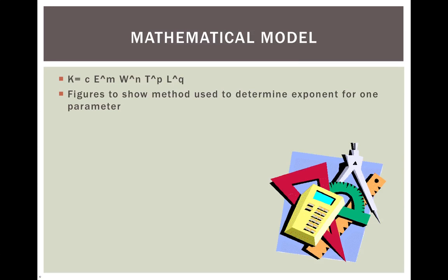But we do not know the values of the exponents for M, N, P, and Q. Given the equation, we figured we should solve it like any other algebraic equation, so we set one variable as the unknown and solved with the other ones being constant. This led us to determine different beam lengths, apply several masses, and measure the deflection, which would allow us to determine the exponent of Q. That is how we started our mathematical model.